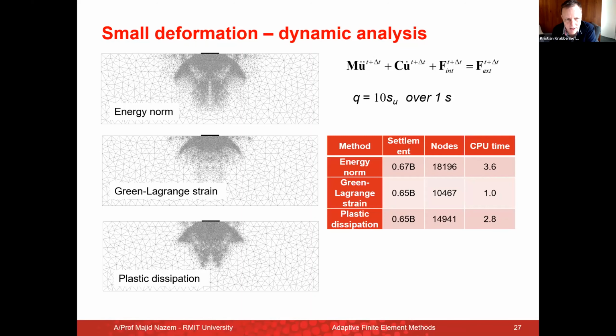Because generating a mesh based on some error estimator is relatively cheap compared to solving the equations. So you would think it would be just a standard technique that everyone would use. But what are really the complications in it? Why isn't it completely the default option, when you use finite element software, to have adaptivity included?